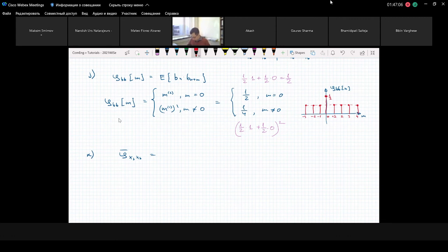Then when you find the corresponding autocorrelation function in the time domain, in the delay domain, you simply take the same shape, but you normalize its discrete pulse and convert it to a Dirac delta pulse. Now along the x-axis we have delay, tau, continuous delay, and instead of discrete delta pulses, we have Dirac delta pulses, which are normalized by TB.